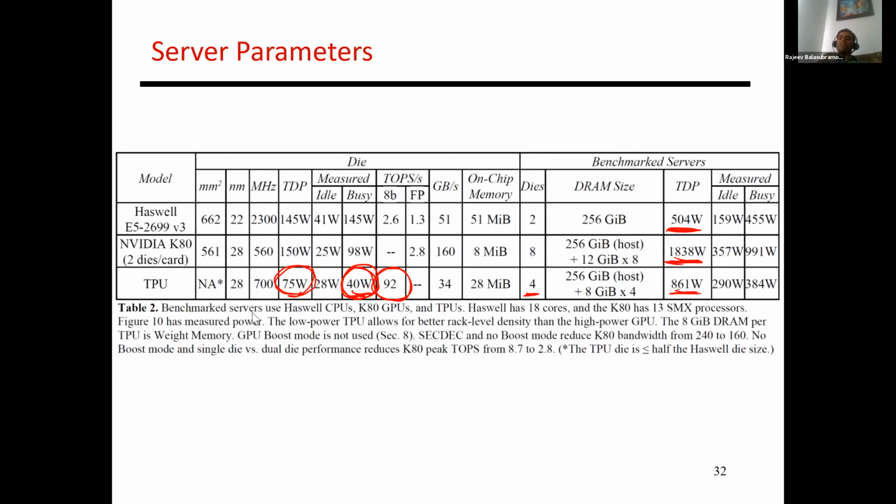Is it true that most accelerators can be accessed only via PCI Express buses? So yes, when these accelerators are add-ons, that is the case, they're usually accessed by PCIe. Again, I've not looked at every accelerator out there, so take that for what it's worth. But the chips that are being designed for training are not usually meant as an add-on to another chip. So the TPU V2, and we'll cover some of this architecture on Wednesday, is basically a torus network of a whole bunch of these chips, right? So most of the communication is happening between these TPUs. It is the inter-TPU interconnect that sees most of the traffic. So it's not the PCI Express that ends up being the bottleneck.